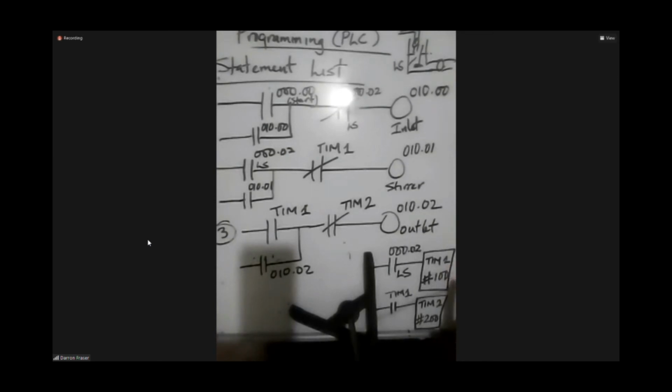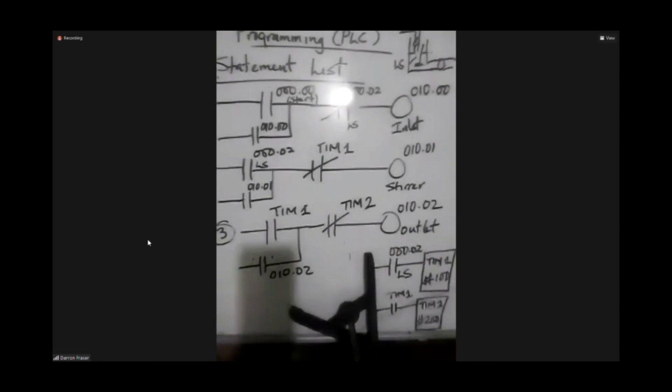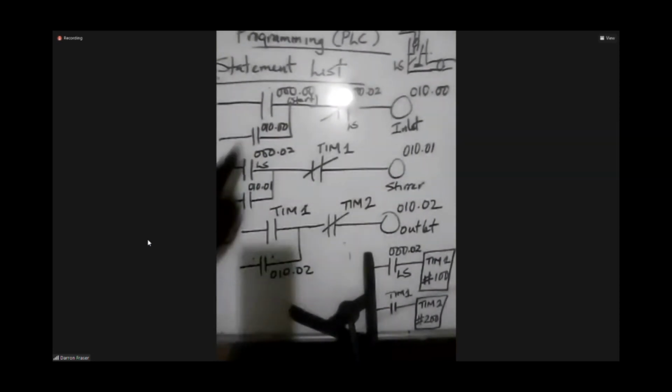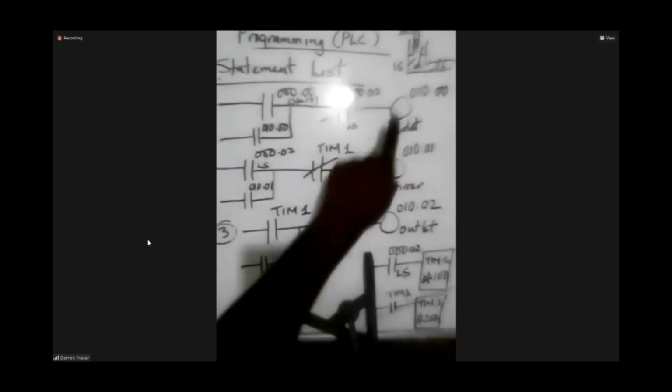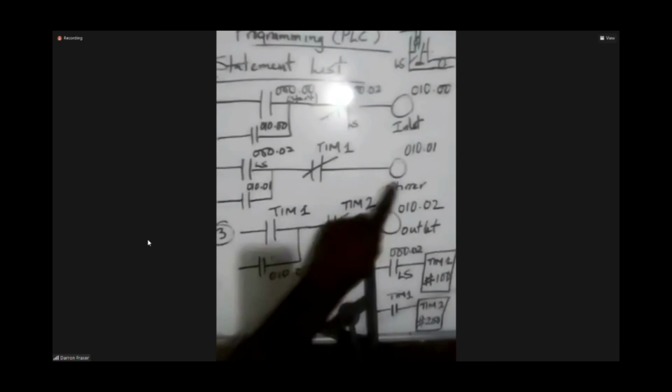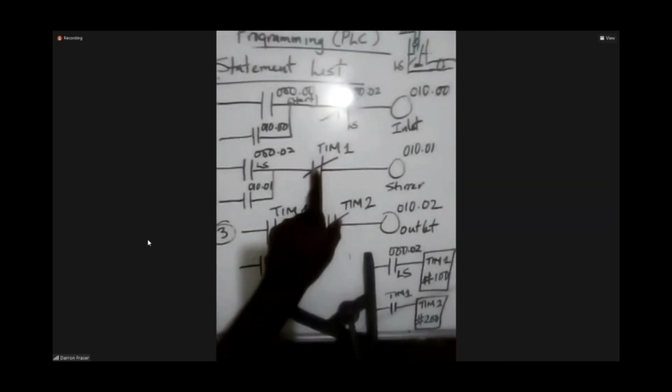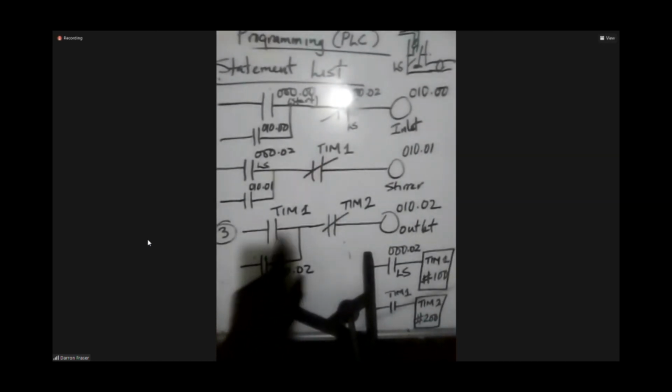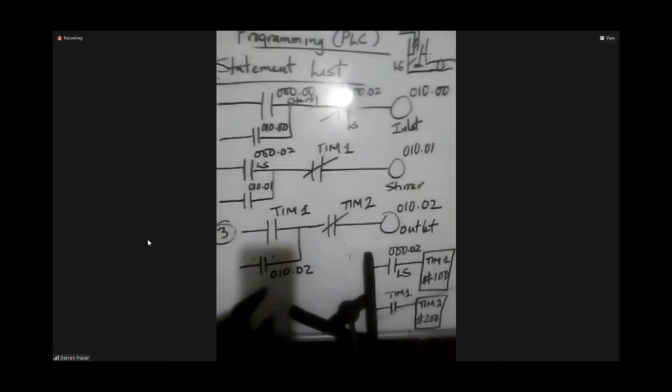Okay. All right. So this is the program that you run. Press the start button, turn on the inlet. When the level switch triggers, it turns off the inlet and turns on the stir. Stir stays on until the timer says timeout. Turn on the outlet, and so forth. But from practical experience, when we run the program, there's a problem. The problem is right here.